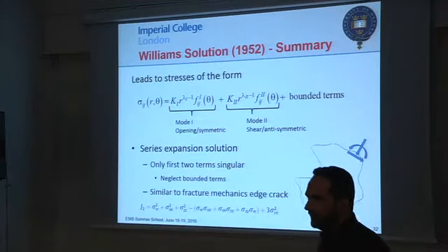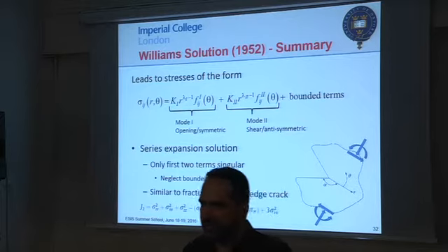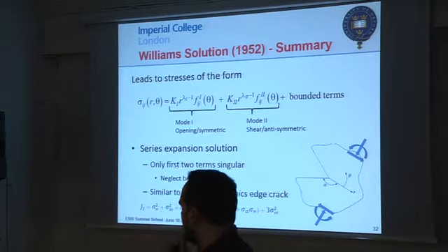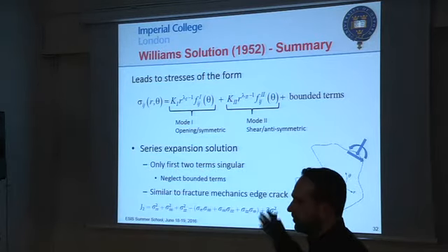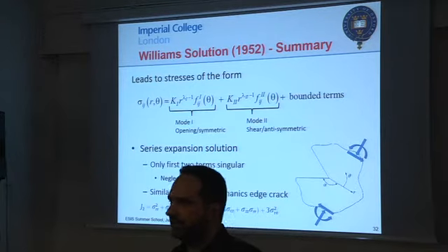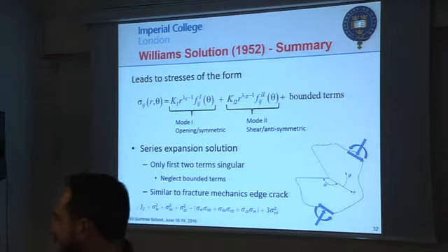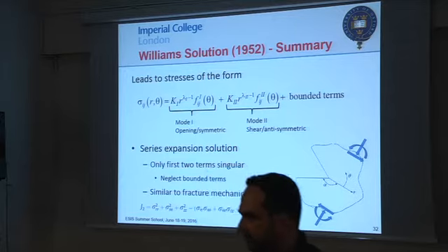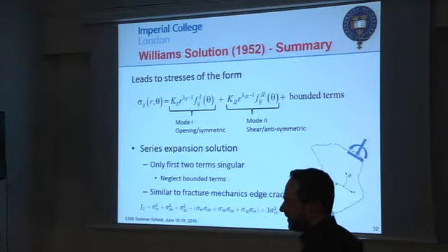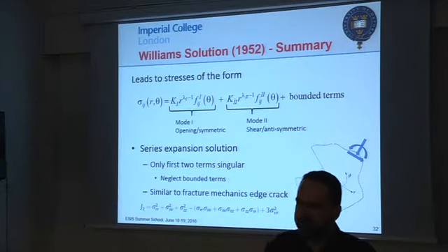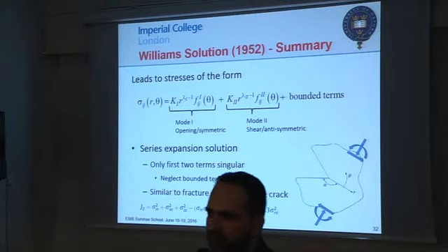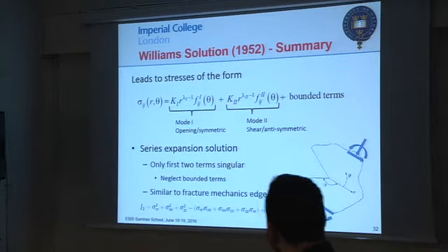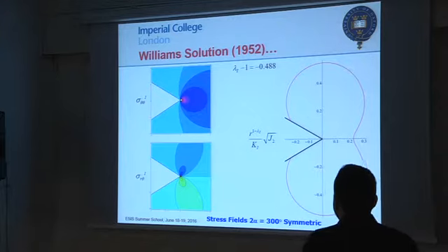And actually, in elasticity, you can also say that when the invariant gets close to the yield stress, then you have plasticity. So you can do all the calculations you do with the crack, saying that the plastic radius can be computed through this.